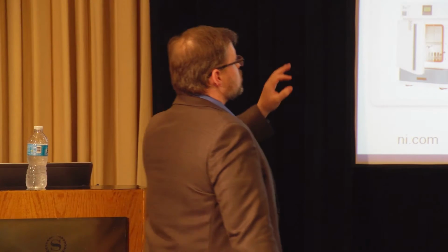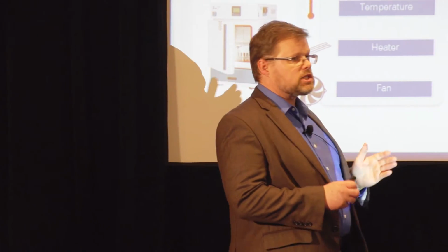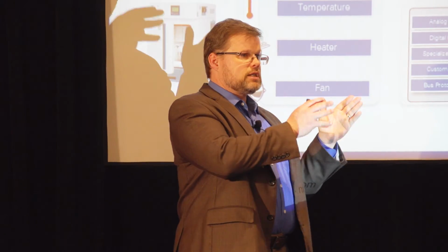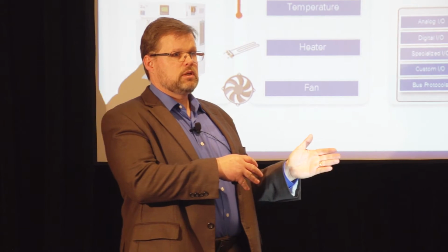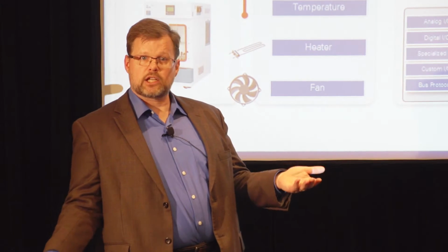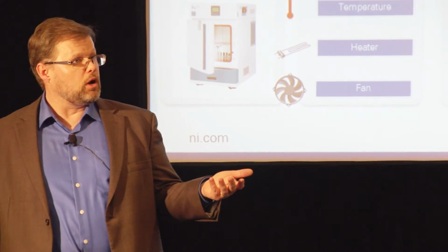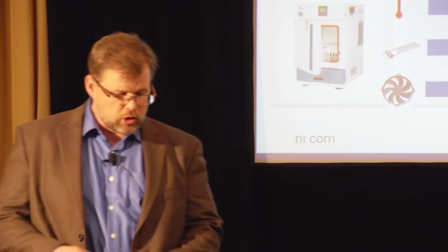And how can your controller know that that has happened? Okay. One easy technique is to actually be testing against the model at all times. And if the model deviates from the actual thing you're controlling, then you know something's gone wrong. And then there could be a whole host of other unpredicted failure modes, including being hacked.